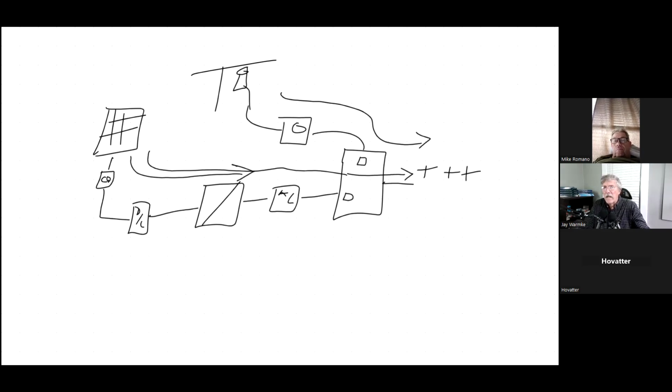So logically, you might say, okay, well, if this is a 5 kW array, I need a 5 kW inverter. And that would work. That would work just fine. But it turns out it's probably not the most efficient use of your resources. We might be able to get by with a 4 kW or maybe even a 3.5 kW. We can oftentimes undersize our inverter, based on the size of the array, without having a significant impact on the amount of generated power. And the reason for this is a thing known as clipping.